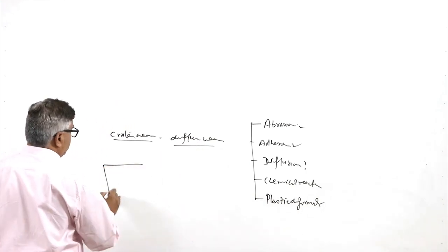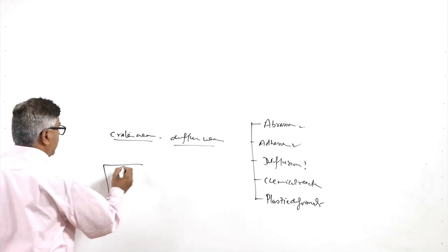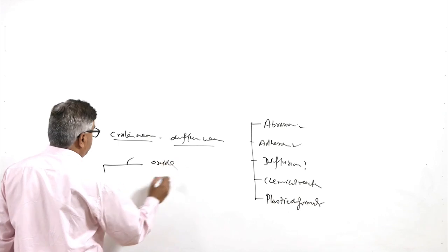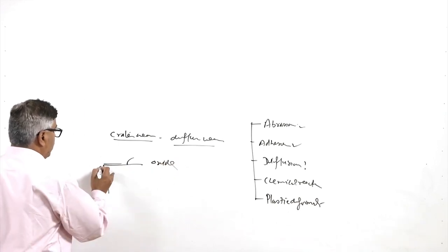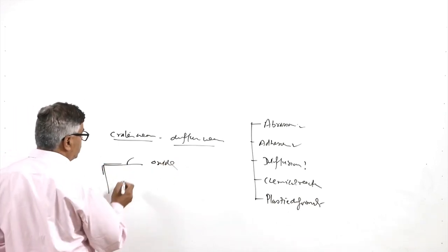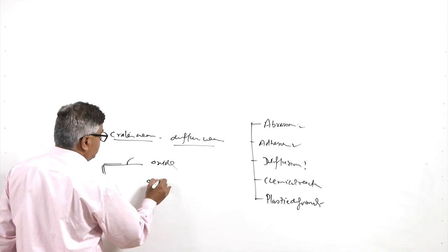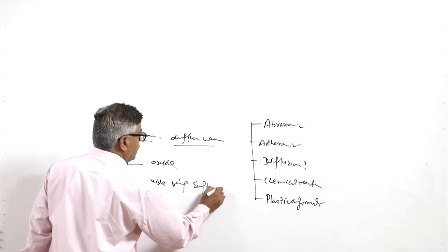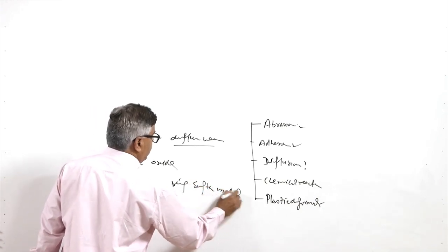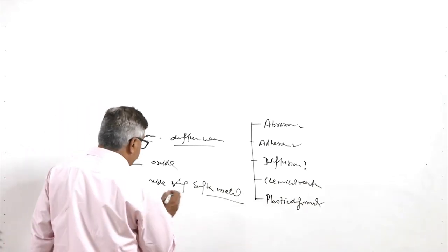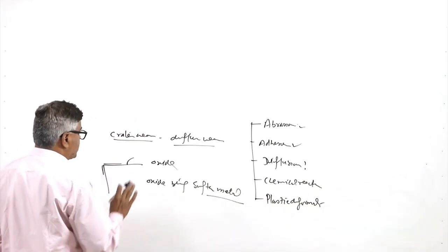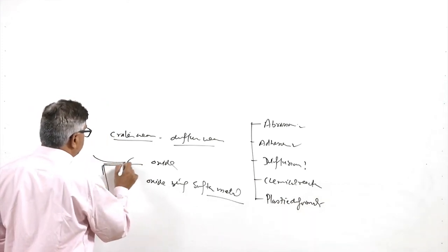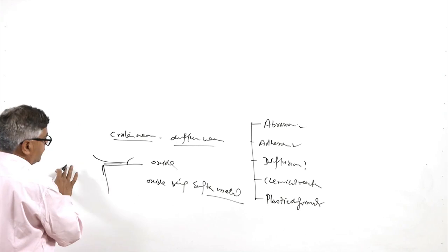Chemical attack is the simple form, where a rise in temperature of the rake face of the tool causes oxidation. An oxide layer is formed at the face and the flank of the tool, and since some of the oxides are softer than the base metal of the tool, they lead to easy removal during machining, due to the movement of the chips over the face of the tool or the rubbing of the flank with the workpiece.